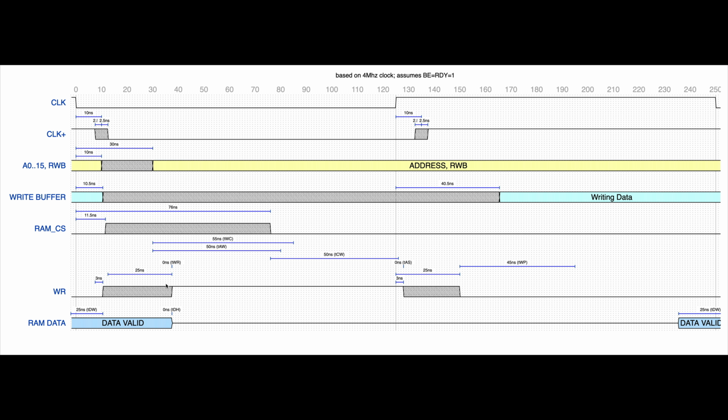The solution to fix this, at least with this new 25 nanosecond uncertainty in the write pulse, is going to actually shift this edge to the other side. So we are currently shifting it to the right 10 nanoseconds. But if we shift it to the left, then we're going to be able to meet the timing correctly. And then it's going to work.